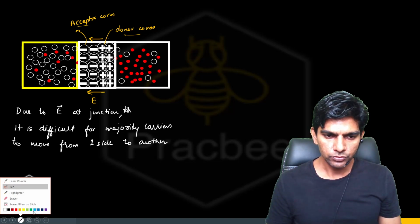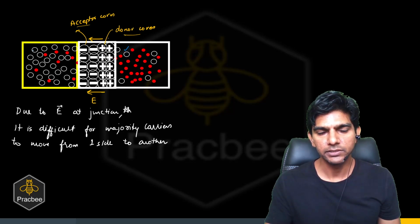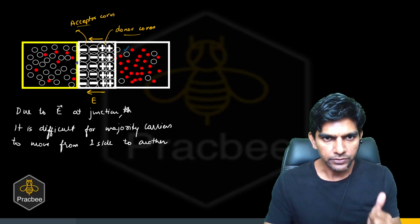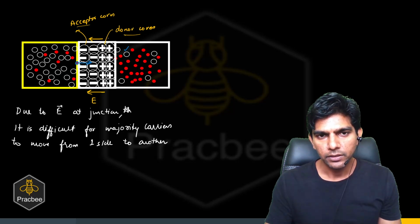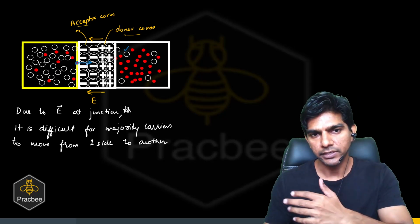But what happens to the minority carrier? If we consider a minority carrier, let us say this minority carrier, on the n side we have hole as minority carrier, on the p side we have electron as minority carrier. So if I consider this electron, which is quite close to this region where we have electric field, now what happens? This electron will experience a force in the right direction, and it will be swept away by the electric field, and it can move from the p to n side.